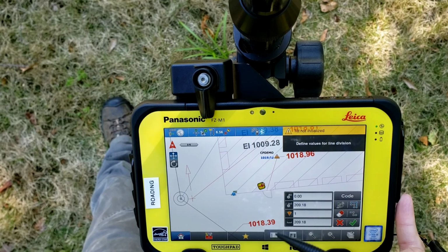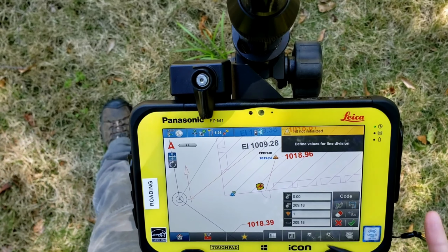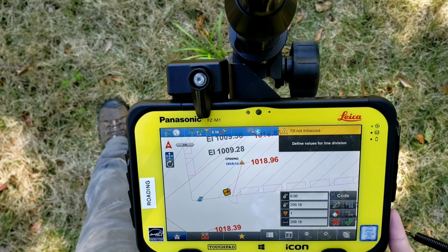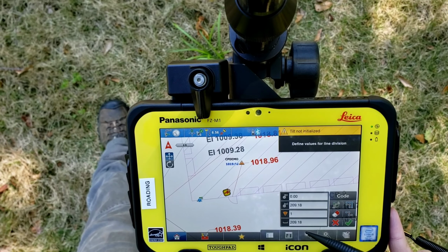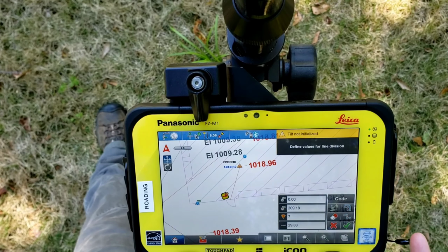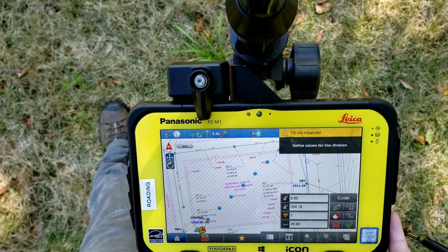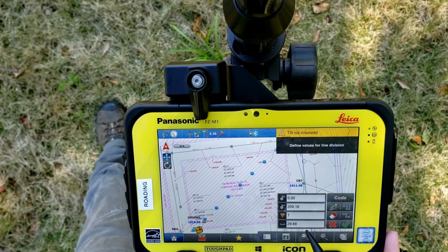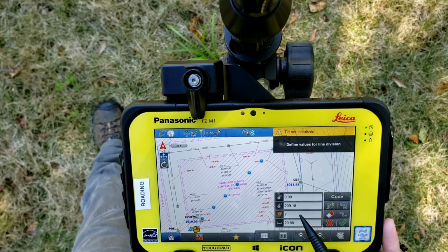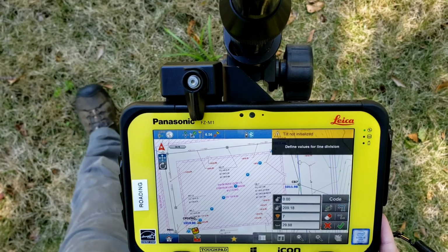But here's the deal. These are segments. If you want to bust up a line into a specific number of segments and prorate them, you can do that. So even though this line is 209.18, say you want to put it into 7 equal segments, that's what that's for. If you put that at 7, you get 7 equal segments at 29.88. You may see these change a bit. If you do 29.88 times 7, it may not equal exactly. That's just due to rounding. The values are correct, but the decimals run out to the hundredth place.